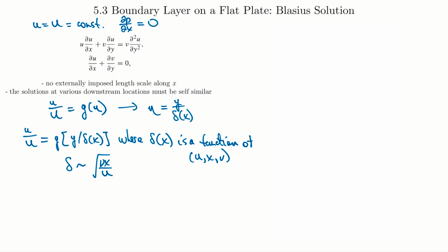Okay, the problem is 2D again, so we can find a stream function, right? We remember again, the stream function satisfies our continuity equation, right? So it's this. Because subbing that in would solve our continuity equation, right? In 2D, Cartesian form. Okay, and then using that, we can get the following.